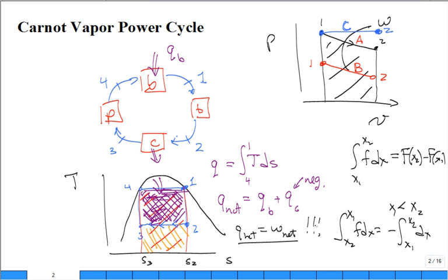Somebody says, I've got a Carnot cycle where TH is this value and TL or TC is this value. Sometimes I use TC for cold and sometimes TL for low. Okay, low temperature, high temperature. What happens if they drop TC but leave TH alone? Is that good for performance or bad for performance? Good. It's good for performance.